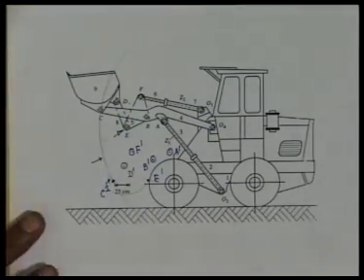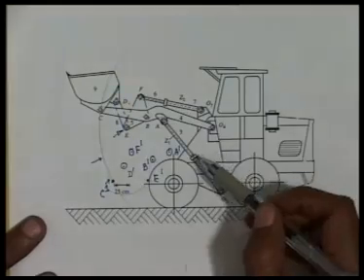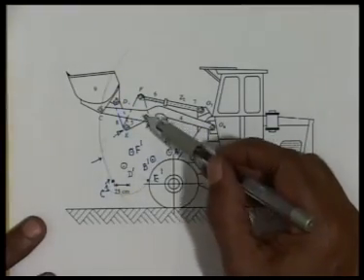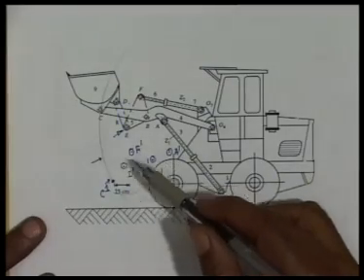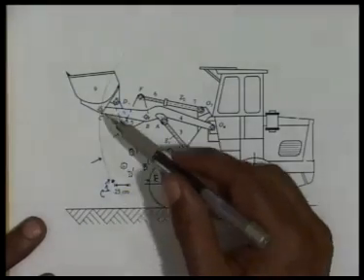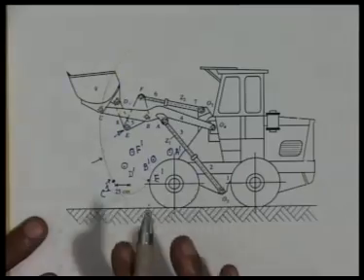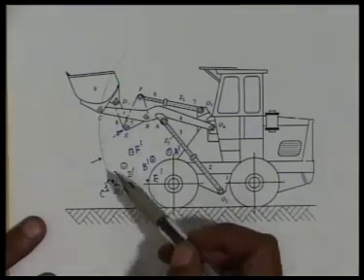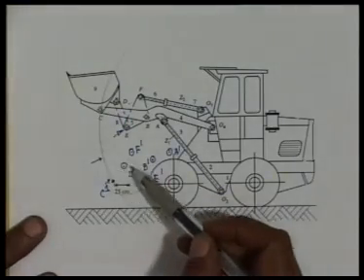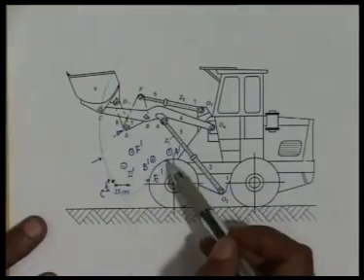So I have determined the location of all the moving hinges, namely A, B, F, E, D, as A1, B1, E1, F1, and D1 of course was given, and C as C1. So we have solved this part of the problem, that corresponding to the second position when D has moved to D1, where all other moving hinges go.